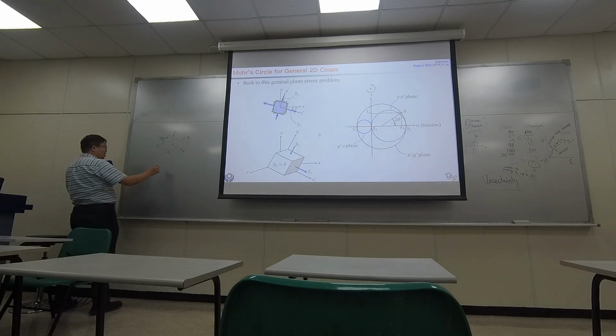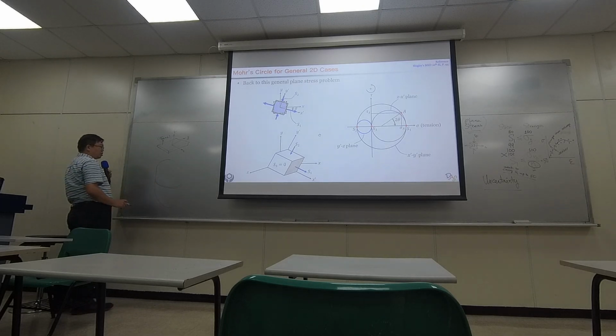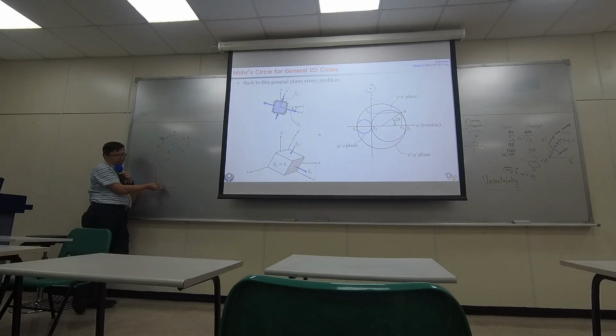And there's another case, which is you have a huge object and you make a planar cut of the object, and because its neighboring plate is carrying identical load condition with your planar cut, if this is the Z direction, the neighboring plate is limiting the displacement along the Z direction of this particular plate.